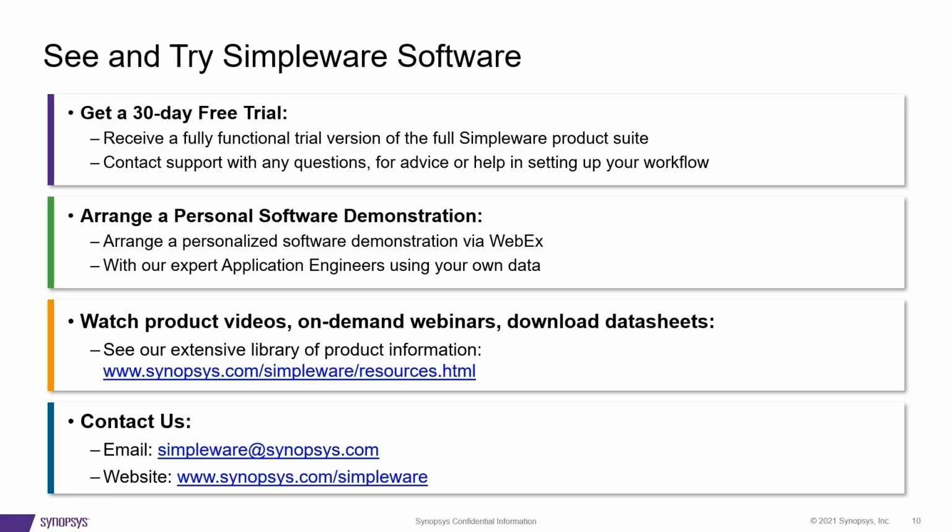In the second slide of my presentation, I showed the accuracy of the applied pressure or boundary condition compared in Simpleware. I compared the STL file from Abaqus, or the deformed shape from Abaqus, with the frame that we had in Simpleware, just to see if the assumptions are correct or not. Since we used some general pressure, we have a little bit of deviation for the aortic part, but for the rest of the geometry, we have a perfect match.